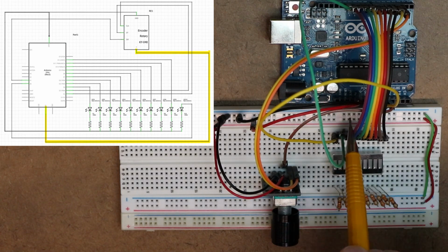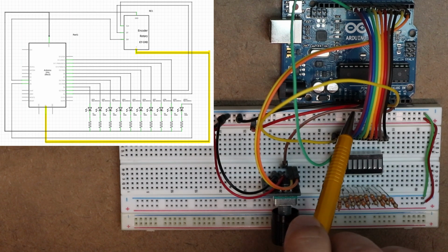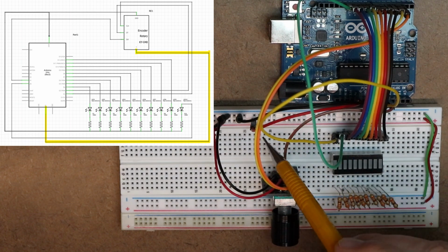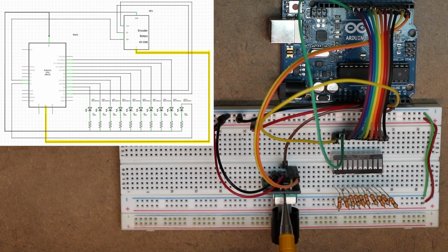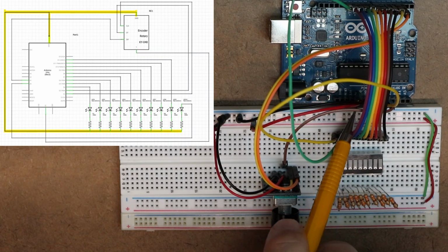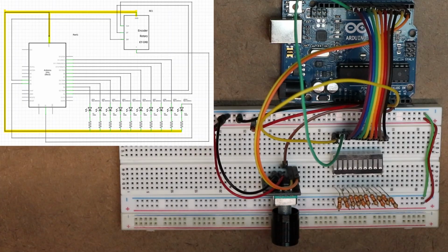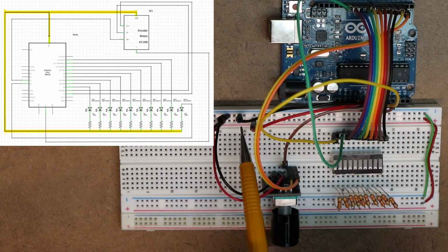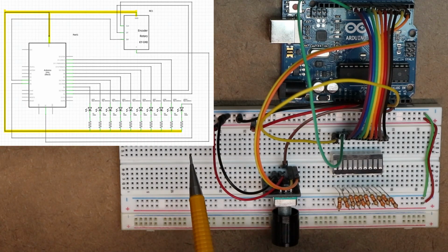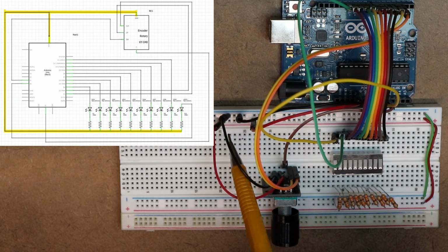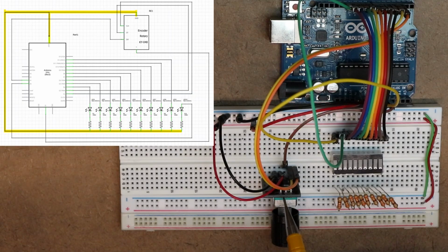So we're going to start with our 5-volt pin of the Arduino with the red wire. We're coming over to our power rail. From our power rail, another red wire coming to our 5-volt or VCC of the rotary encoder. Next we've got our black wire, which is in the ground pin of the Arduino right next to that 5-volt. It's also coming up to our ground rail, and then a black wire coming from the power rail to the ground of the rotary encoder.